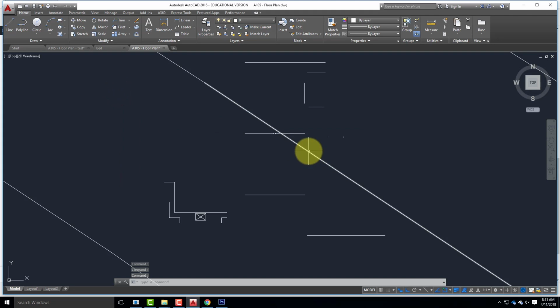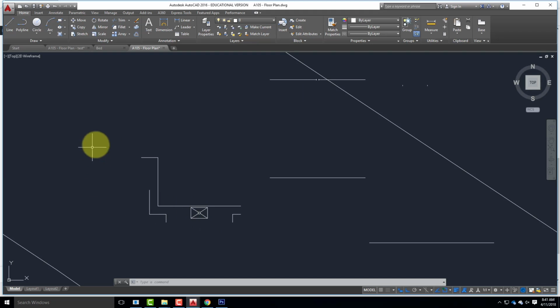So as I start to look at what's left, there's a lot of things that are just kind of leftovers. So for example, I have a kitchen sink and I have some counters that are in here that are available. I need to put those on some kind of a layer, and I need to think about what I want that layer to be called. So typically, we have 2 more layers that are commonly used in practice, A-furn for furniture and A-fixtures for fixtures.